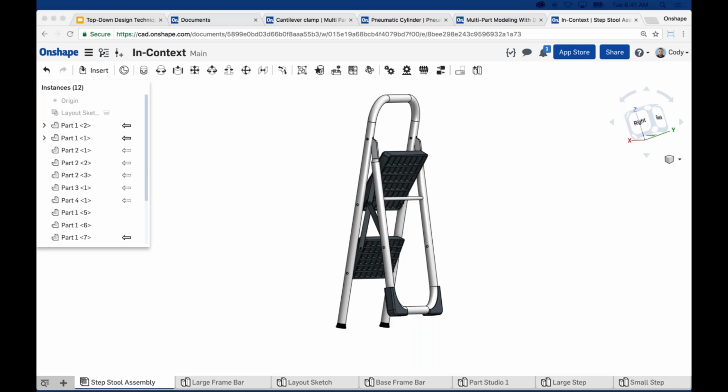Questions. If I edit in context to create a base sketch and then model multiple features based on that sketch, then later change the assembly and update the context, will all subsequent features update based on the contextually updated sketch? Yes, and that's a good technique.